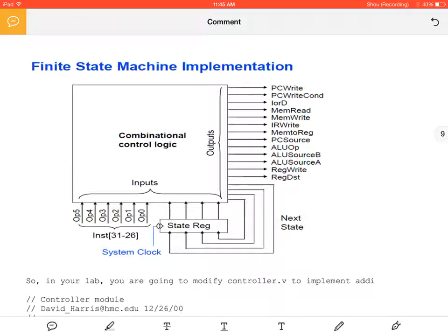So what's happening is, at every state, you have the instruction value, and you're only overwriting this when the IR write becomes 1. Otherwise, it's holding that same initial value, right? So if it's an R-type instruction, it's going to go to 0, 1, 2, 3, 4, and then in a finite state machine, the next state register is going to update the values. So it's going to make that decision, go to 9, then go to 10, and update these outputs accordingly.